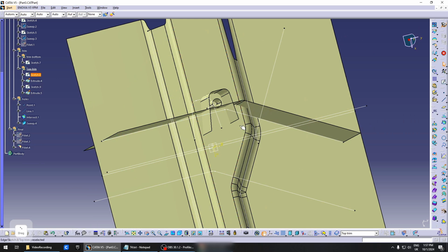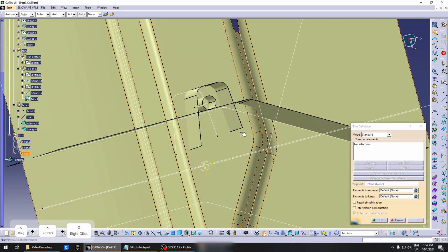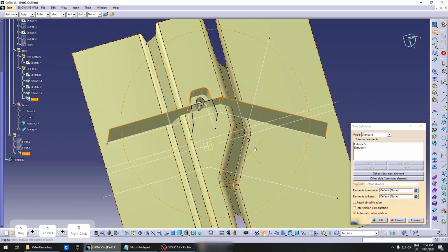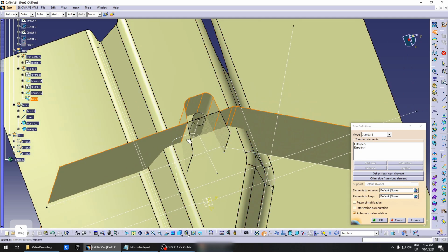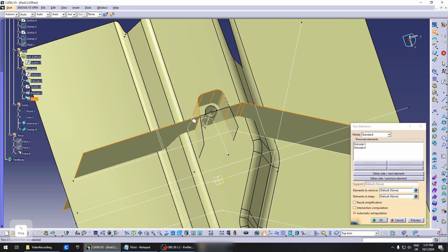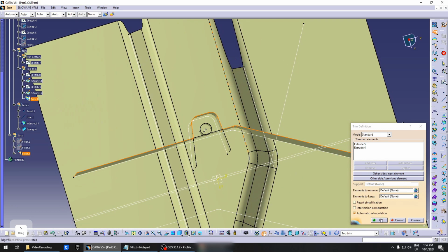Now you have this feature here, and you can combine these two shapes. I can show you a different way to combine them now. It is with the trim command. You select one of the shapes, you select the other one. You can select more of these and it will just trim them all. And you can already see that it basically cut through this middle part here, and it made a combination of the shape.